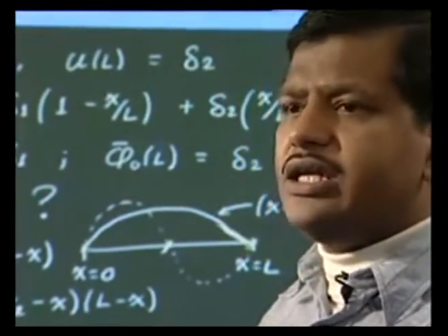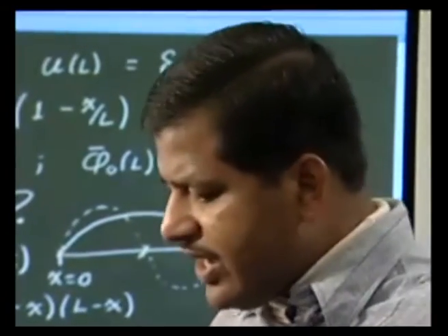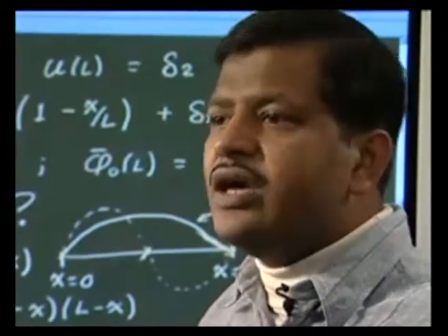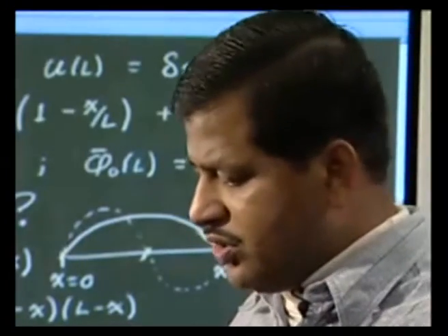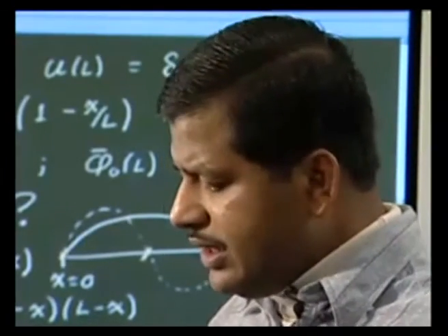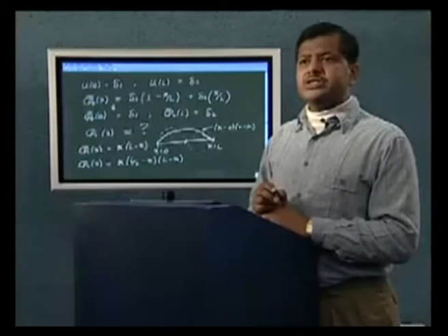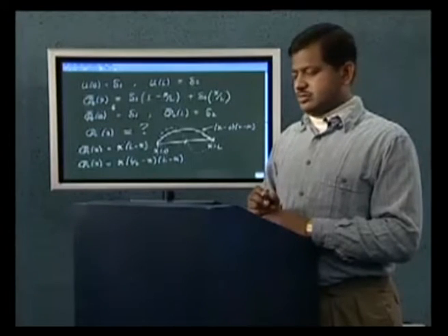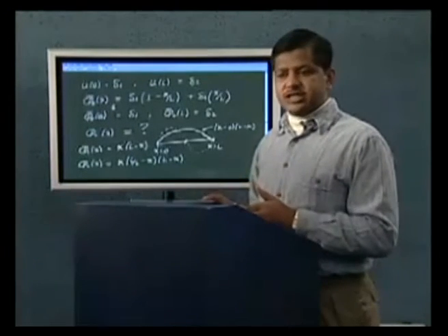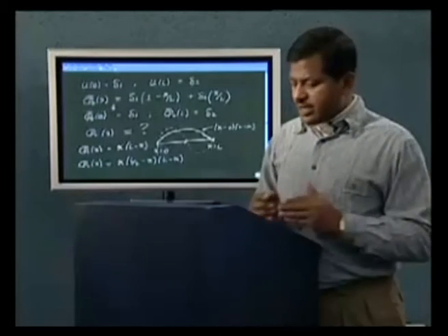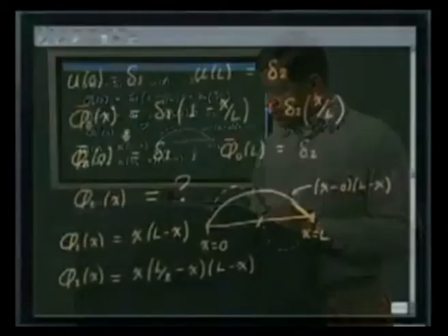What I want this function to do is vanish at the point x equal to 0, at x equal to L by 2 and at x equal to L. So I get a cubic expression, and so on. I can keep on constructing these phi i's, which are polynomials of increasing order, by choosing appropriate points where they vanish. Once I have done this construction, I will put it back in my expression for un of x.